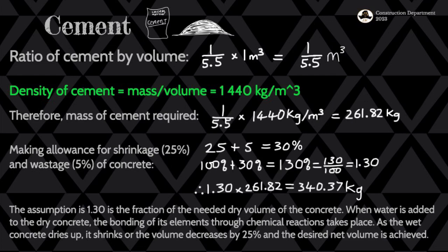In order to achieve that 20 megapascals, you need the quantities in the ratio of cement, sand, and aggregate, which is stones, with the ratio 1 is to 1.5 is to 3 respectively. Cement, sand, aggregate 1 is to 1.5 is to 3. So that's the ratio in terms of their units or quantities.